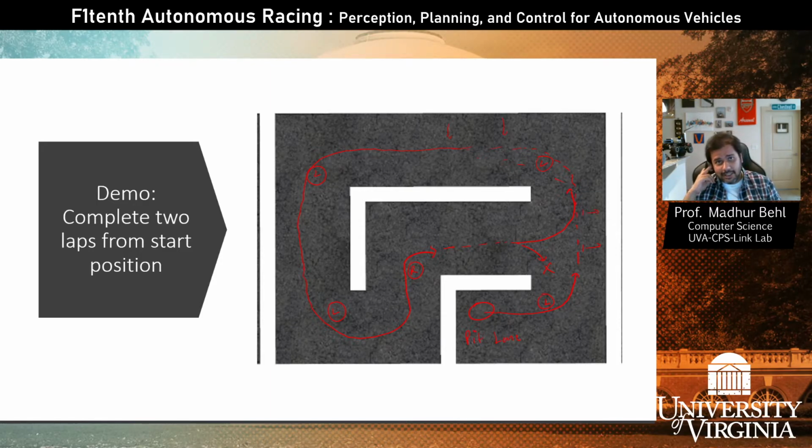There will be a live demo, meaning we will have teams log on to the server, and together with the TAs, we will run your code live and see the behavior of your car in a live virtual online session. On top of that, you have to submit your code as well, because we will verify its correctness. That, in a nutshell, is the wall following assignment. It's a very exciting assignment. It's also the simplest thing you can do in the simulator, but it'll take you some time to tune these PID values and make sure you are scaling the error terms appropriately, and so on.